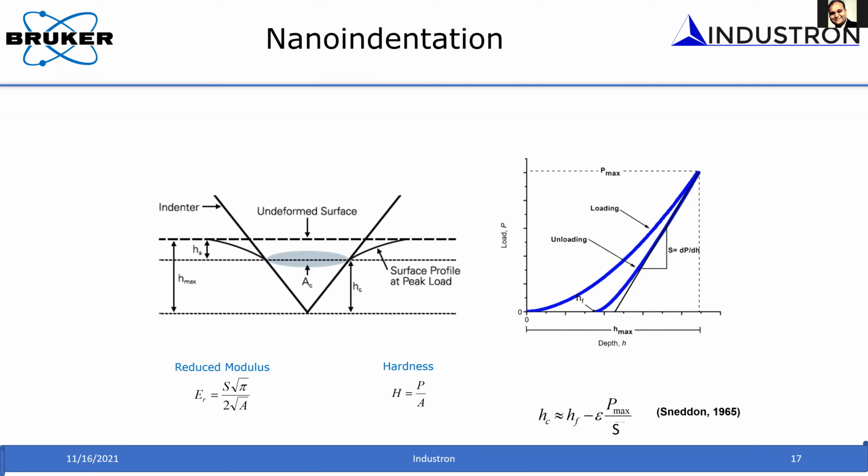It is easy to say you measure the load and measure the depth from the load displacement curve, and you go and measure the hardness of the material. It is easy to say. To make a consistent, repeatable and valid measurement, there are a lot of procedures you have to go through. You can research them on the web. There are a lot of papers, and there are procedures and calibration routines that you have to go through to calibrate the indenter probe and the indenter system.